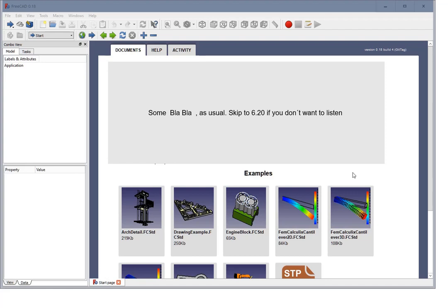So as long as this is not solved, 0.18 is the version to take, especially when you want to learn FreeCAD. If you don't want to use the Part Design, or you don't need these named constraints or any references, you probably don't even want to use the formula editor, well, you're fine with 0.19.